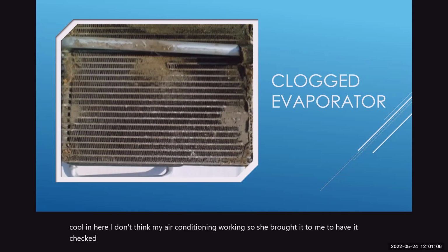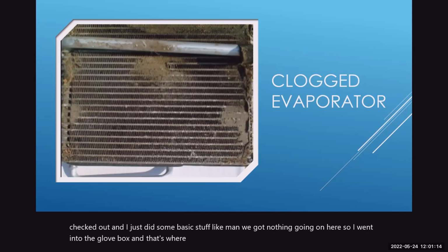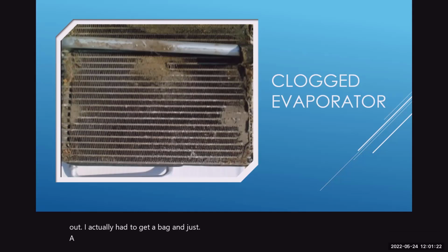And I just did some basic stuff. I'm like, man, we got nothing going on here. So I went into the glove box, and that's where the filter was at. I pulled it out, and I could barely pull it out. I actually had to get a plastic bag, and I had to move it back and forth and almost force it out.